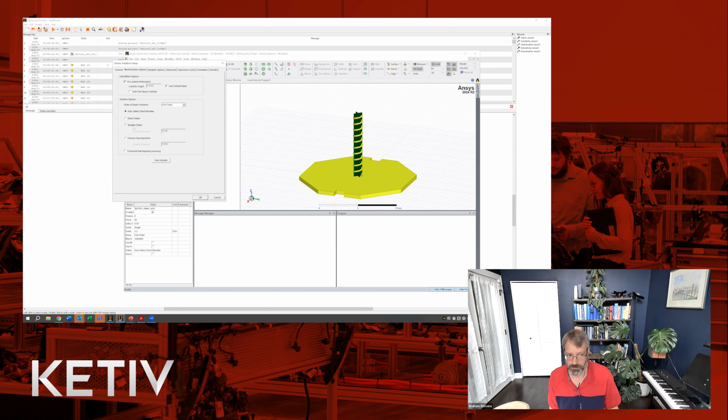I might use the direct solver, the iterative solver, again, depending on which one's faster. So I might do save fields and save radiated fields only to reduce the amount of disk space that each analysis takes. So there's a number of different steps you can take in here.